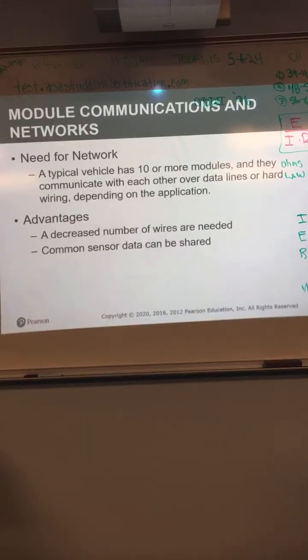So let's say the emissions on it were bad. If I were to just throw on a new exhaust system and take it up there, I'd be fine? Depends on what was wrong with it. If the HC was high, if the CO was high, if it was running rich, or if it had an electrical or ignition system problem, depends on what it is. If it fails, they used to give you a printout of where it failed, what was high, and the standard for that year.